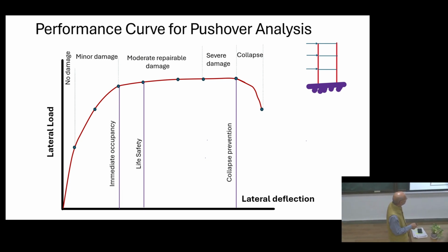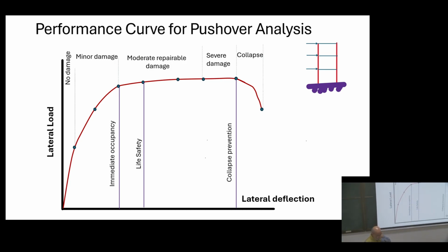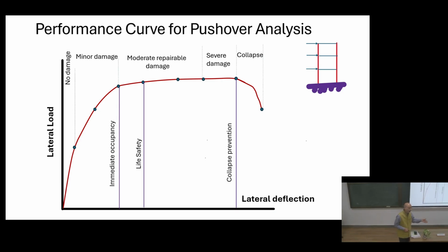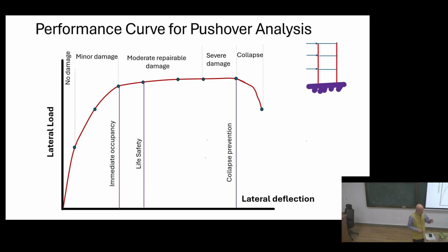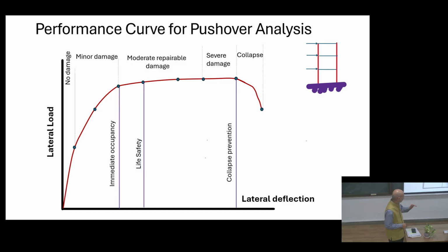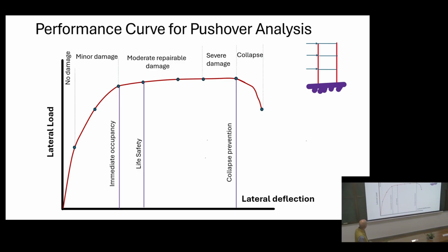So suppose you have a building. As Professor Datta mentioned, when using this curve, even from the code, use it as a single degree of freedom. That means a multi-degree of freedom system you convert into a single degree of freedom, and then you can use the response spectrum. You probably started using the response spectrum in your structural dynamics course as well. Even the code has the same thing. So when you do it, I made it this way.